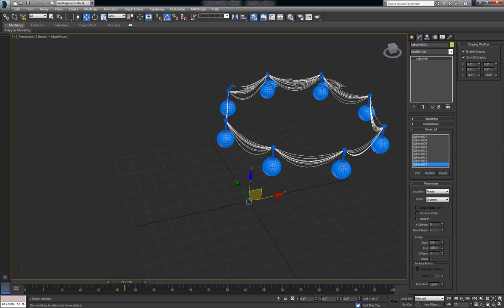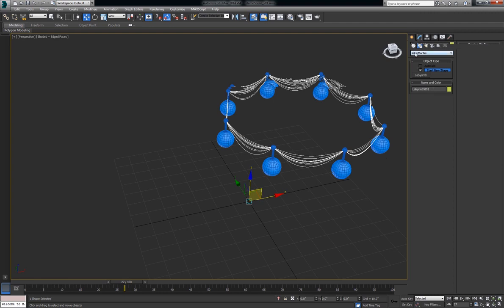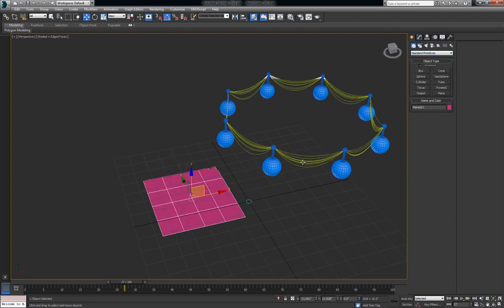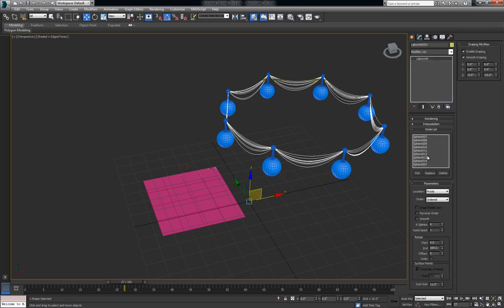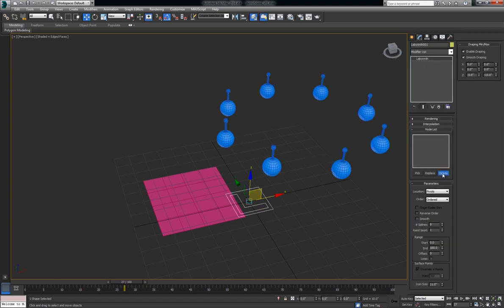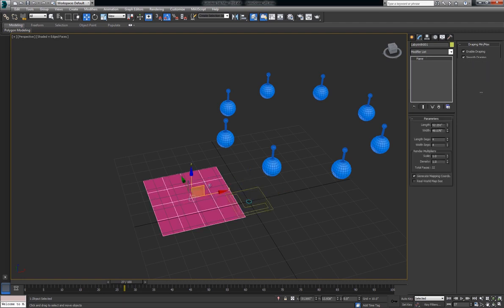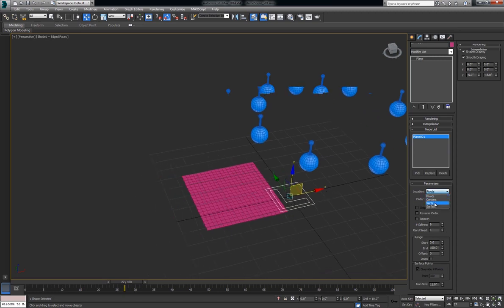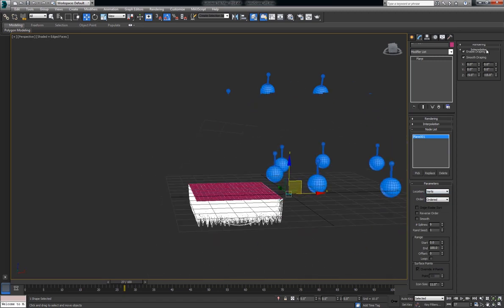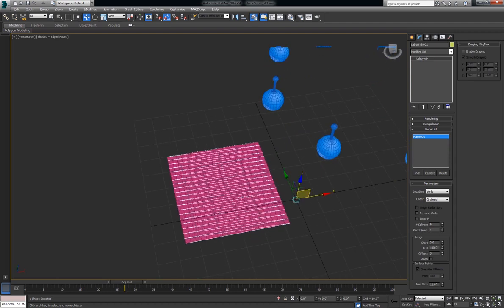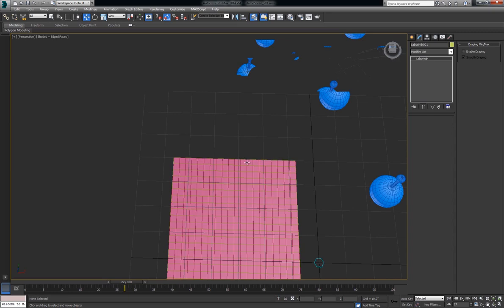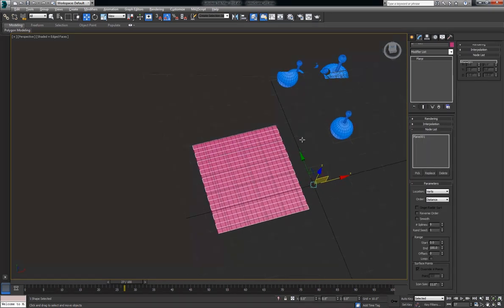Next, what I'd like to show you is the fact that Labyrinth, like I said earlier, works on surface deformations and animated objects. So we'll move all those. We'll click this here and we'll make it a little bit more tessellated. And we'll do verts. We need to turn off draping, even though it may look cool. And we'll do distance. There we go, click our spline here.